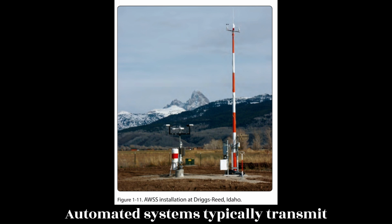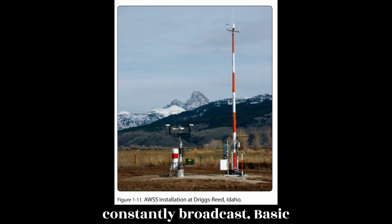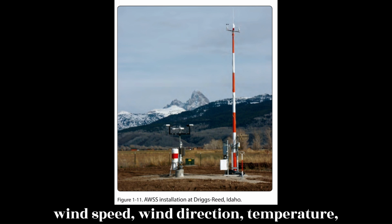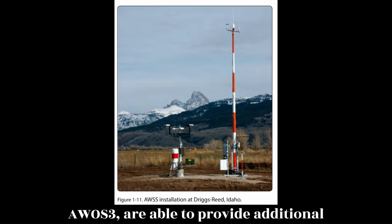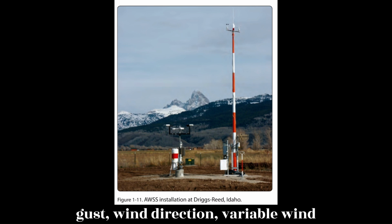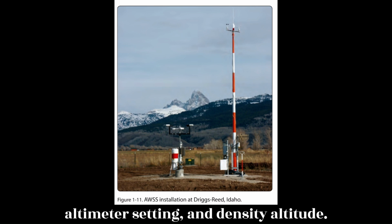AWOS and ASOS/AWSS offer a wide variety of capabilities and progressively broader weather reports. Automated systems typically transmit weather every 1 to 2 minutes, so the most up-to-date weather information is constantly broadcast. Basic AWOS includes only altimeter setting, wind speed, wind direction, temperature, and dew point information. More advanced systems, such as the ASOS/AWSS and AWOS3, are able to provide additional information, such as wind gust, variable wind direction, and density altitude.